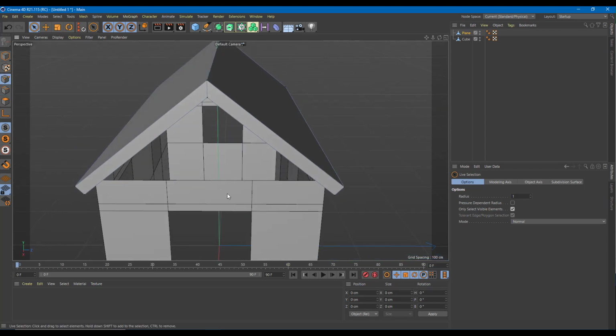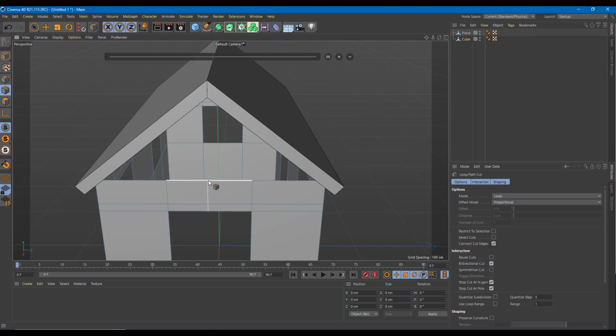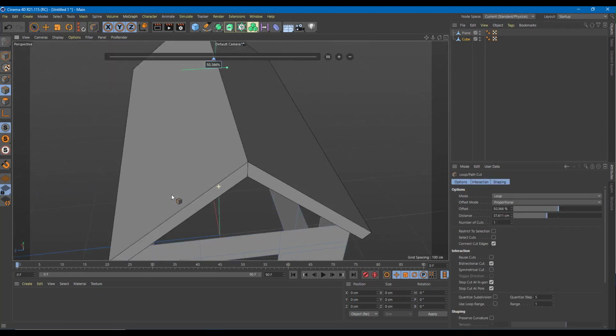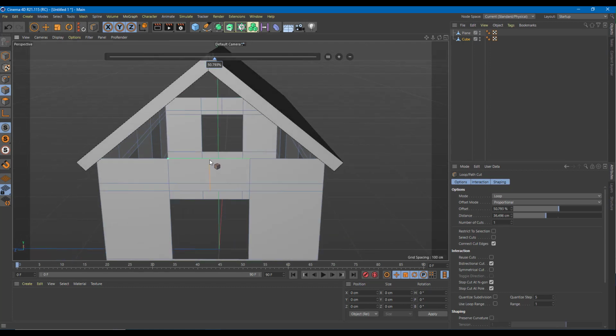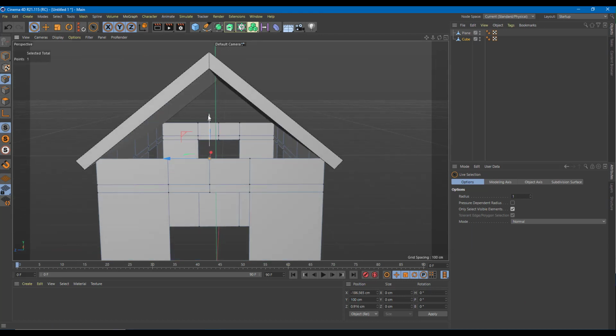And so I want to select the cube right here, and I'm going to go over here onto the S selection again, and then I'm going to press KL to bring out the loop tool. So I'm going to click one over here and another one over here, just like this. Then I'm going to select my selection tool. I'm just going to bring this up just like that.